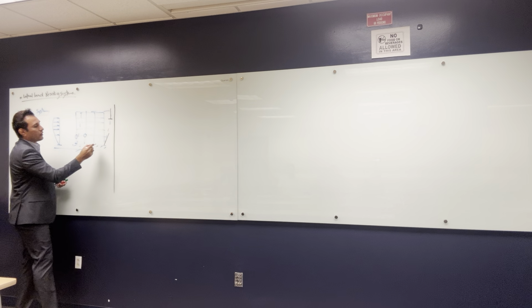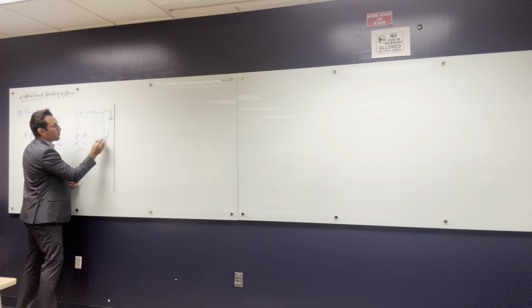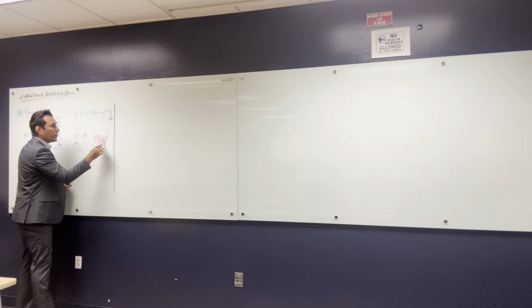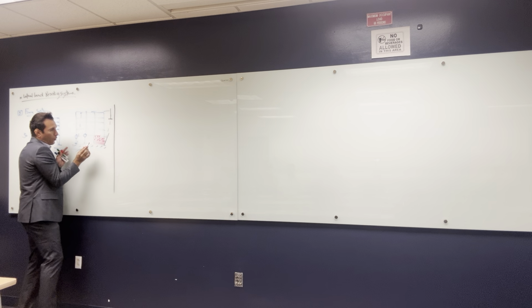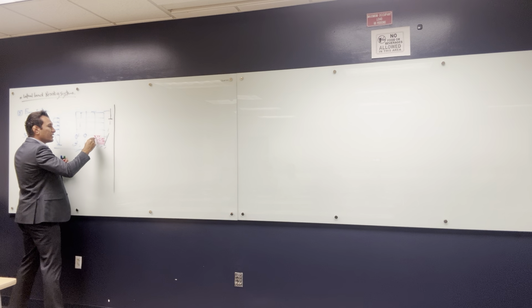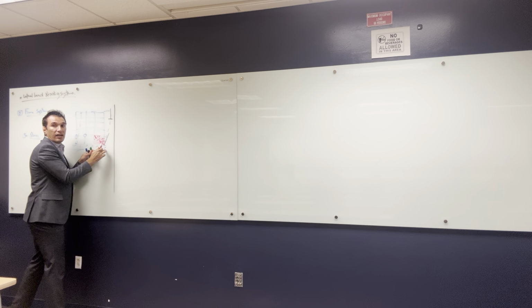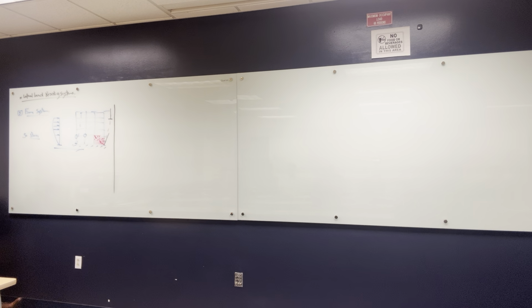And we talked about the infilled frames. Infilled frames, so when you start to use brick walls, and we use this in the resisting system. So when this system wants to shift that way, it's gonna create strut and tie action inside the brick walls, and it's gonna add more resistance to the building if you included the walls or the brick walls to resist the lateral loads.